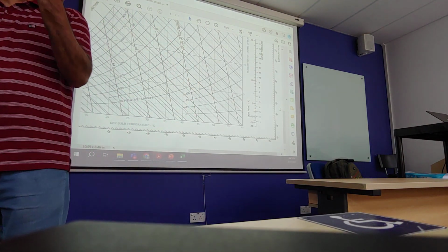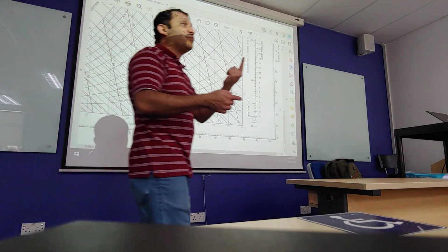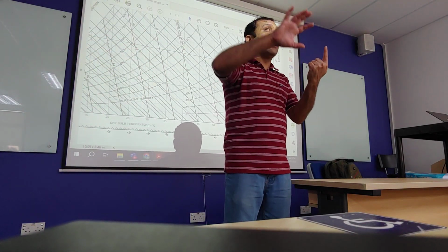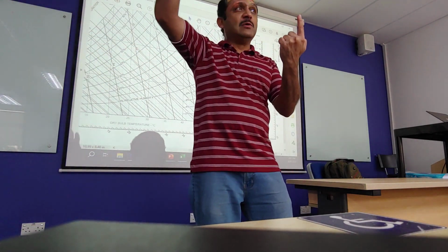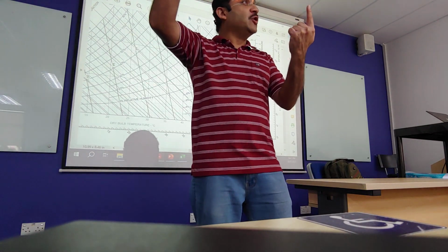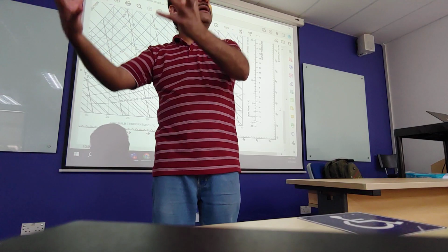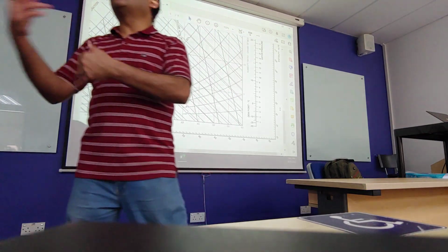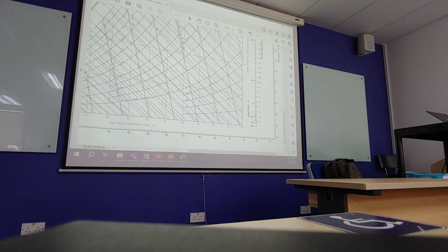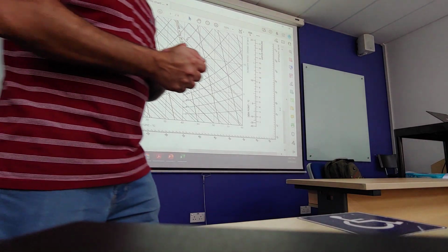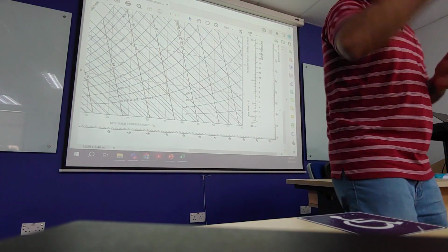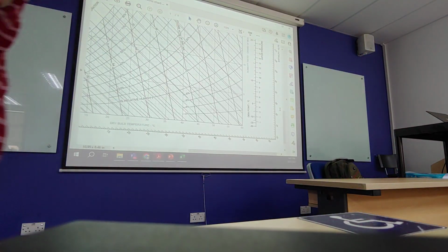So then the most likely cause is, what type of dehumidification system do we have? Are we chilling the air? Are we cooling down the air to its dew point temperature to remove the moisture? Or are we using chemical desiccants? Have you heard of chemical desiccants? What's meant by a desiccant? What do you mean? Take out the moisture. Take out the moisture, yeah?